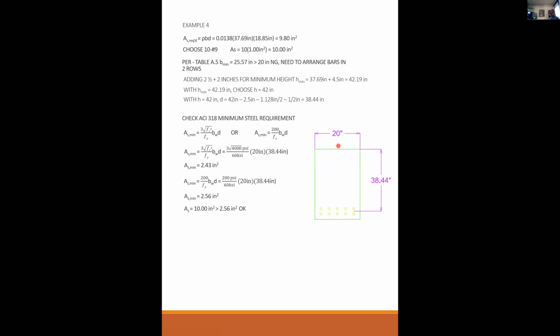Doesn't change anything. But what does affect the structural performance is if these spaces are too tight, the concrete pours down from the top and gets hung up on them. And then you get this effect that's called segregation, where all of your rock clumps up on the bars and only the cement and water kind of bleed in through, and that's not good.